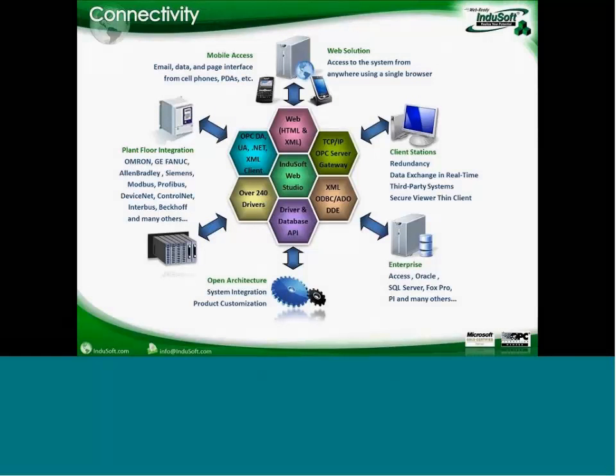But in cases where you have a device for which we do not have a native communication driver, or if you have several systems that need to communicate with that device, then an OPC server makes sense, and we fully support different specifications from OPC. All the main current ones, including OPC-DA, .NET, XML, and UA. We provide an open architecture with APIs, a state-of-the-art interface to databases. We even have a patent that allows you to save and retrieve data from SQL relational databases, and tools to exchange data between two or more stations running InduSoft Web Studio.